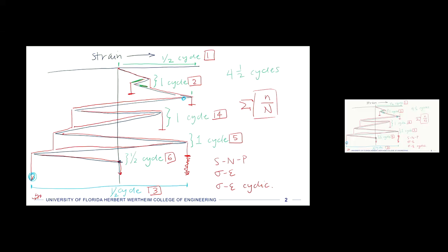And then you would know that a crack would initiate if that sum became greater than or equal to 1. Okay? So you can see how it might start to come together. It's not a very simple process, but it does have some detailed methods for each stage to go through and then assemble into a larger model to see if you would get fatigue or predict how many cycles you have left before you would initiate a fatigue crack.